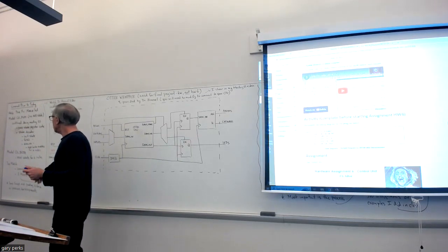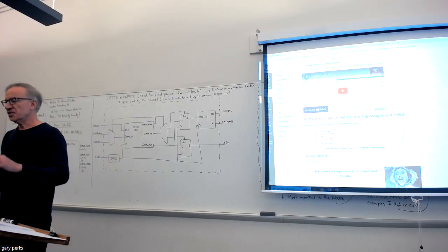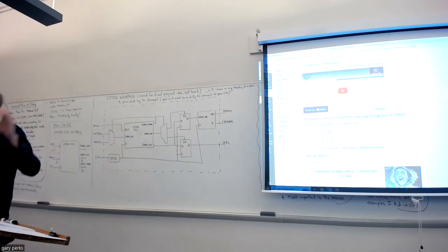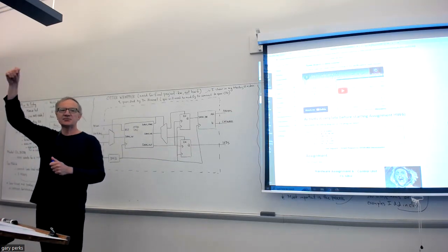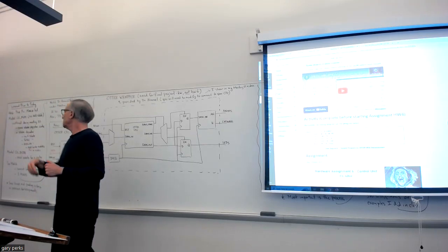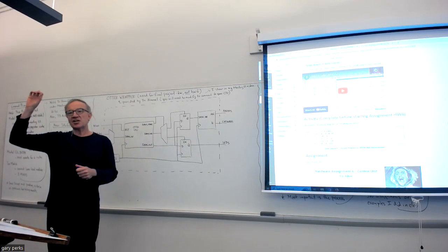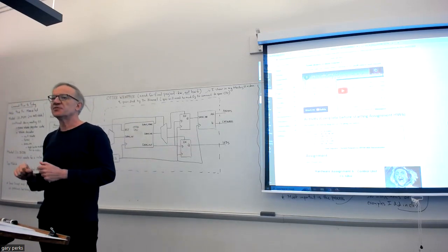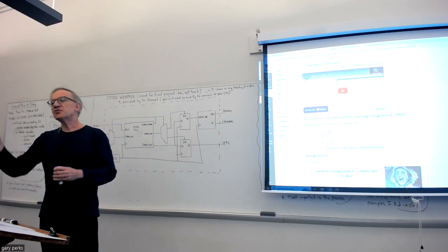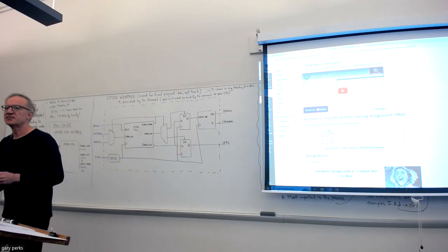In addition, you need 3 more muxes. You've done the mux for the program counter, but there are 2 muxes at the input of the ALU, and there's also a mux at the reg file, for the write data input. Like I mentioned last time, you could put those muxes in the top module. You can put case statements right in the top module, one case statement for each of the muxes. Or you could just use a design source file for the mux.